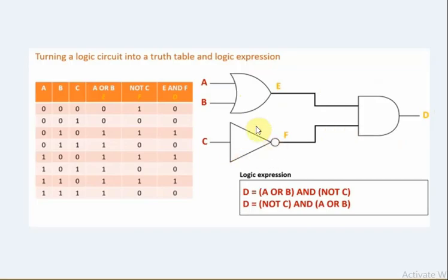So the firefighter is not doing anything. According to this, we should turn on the alarm, no? So to turn on the alarm, this needs to be 1, no? So therefore the firefighter signal should go through a NOT gate. He is not doing anything means 0, no? So not doing anything, this needs to be always 1. Then only either this or this, you get 1 here, then the alarm should go on.